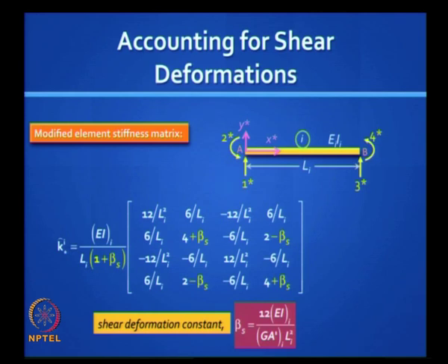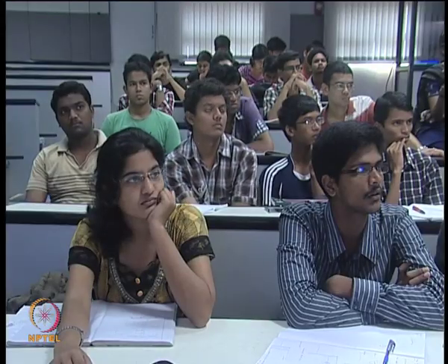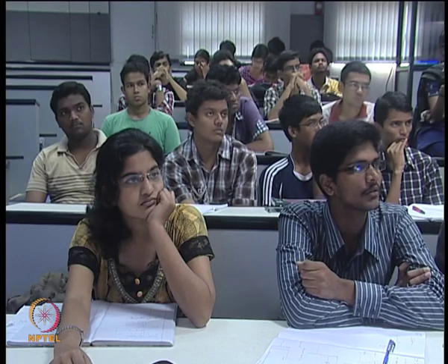One last topic before we move on to reduced element stiffness method. Sometimes it becomes necessary to account for shear deformations. When do you think you need to account for shear deformations? Length is very small. When the span to depth ratio is low.